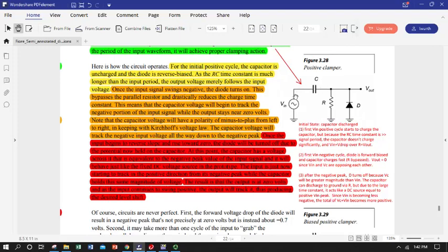When we try to swing back negative, we can flow current. And so we're literally going to be building an opposing voltage to our first negative cycle. So the output's literally going to see the sum of the input, which is going to be negative, and a growing positive V sub C, which is going to cancel out. V out is going to be negligible.